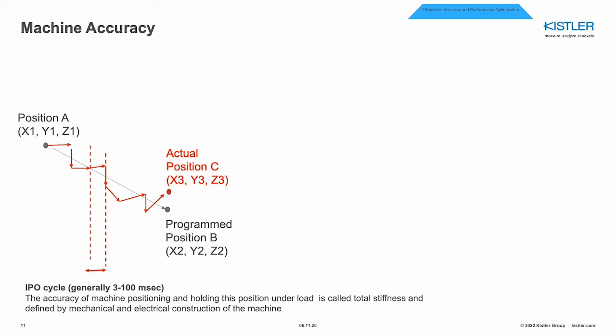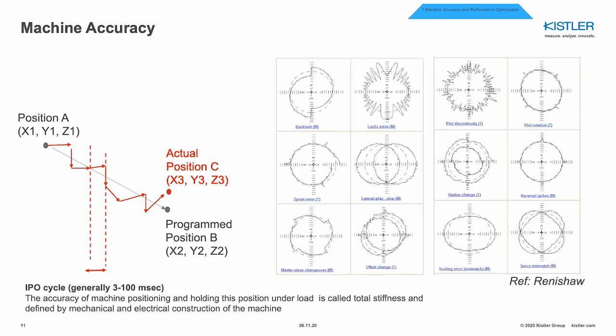So it's very, very important to understand first the accuracy of your positioning in your manufacturing equipment. And one of the easiest ways is to utilize two axes which are perpendicular to each other and perform circles. For instance, as you can see here, because you will realize that the machine is making certain errors, and that will affect your process.